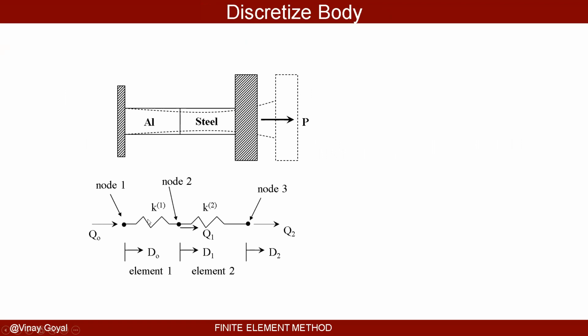So that's element number one. That spring is going to be representative of this actual bar that can be deflected. This bar cannot take any lateral loads, just axial loading. So that's why a spring makes sense, because a spring extends just like this 3D bar. So that's element number one. For the steel, we're going to use element number two.